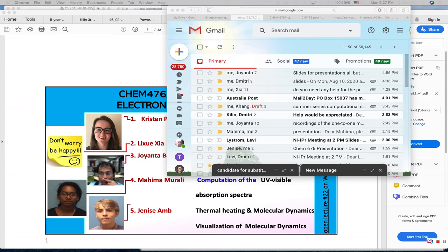The first one is ISPIN. I would like to change ISPIN to 2 when I deal with magnetic systems, which usually contain transition metals, such as iron or cobalt.